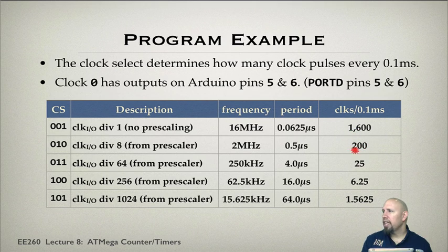So why don't we use an even larger one? Well, this only requires 8 bits, so we never have to go above 8 bits in order to use this. So 200 is actually a good number. Anything above 100 is probably good. Less than 255, so between 100 and 255, that's a good choice to make. So we're going to choose this as our prescaler.